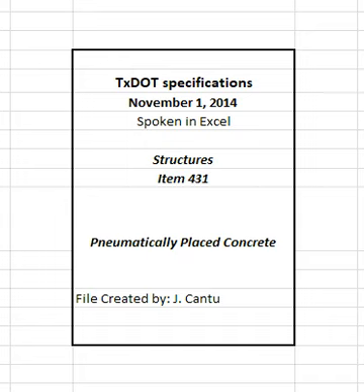Clean the surface to remove the thin film of laitance to provide for a bond with succeeding applications. Remove rebound and accumulated loose sand from the surface to be covered before placing of the original or succeeding layers of concrete. Correct any sags or other defects to the proper section as directed. Place concrete to completely encase reinforcing steel.